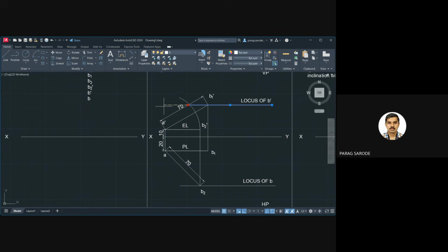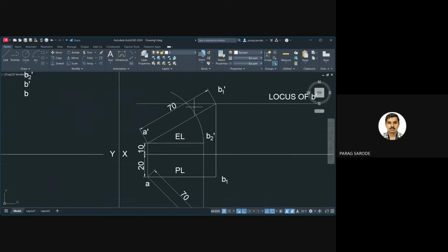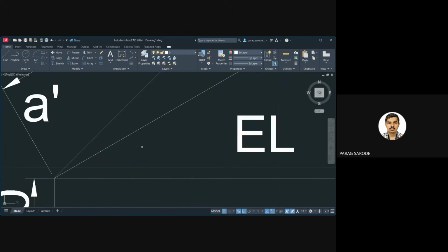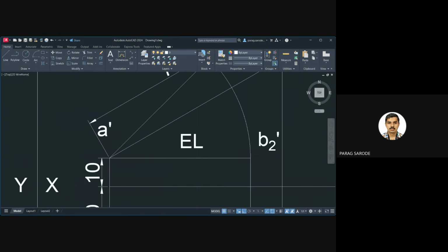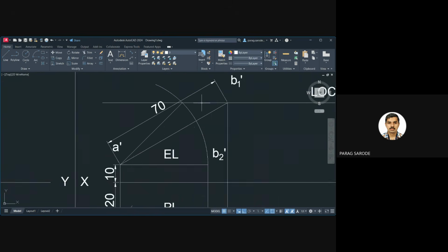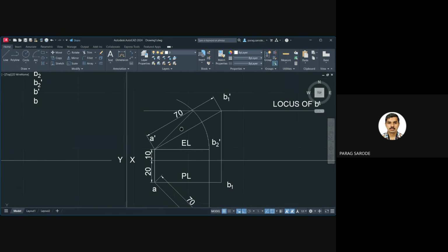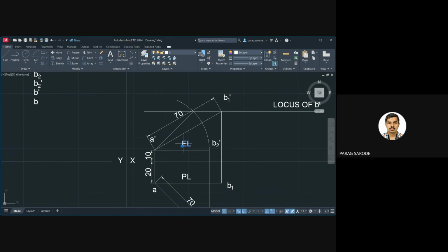Ortho mode on first before stretching. Like this. Can you see the intersection we want? Like this. While joining, carefully see whether you have joined it correctly or not, and by enlarging it. Now, what is this particular line? It's a front view length, correct? It's the front view. We'll copy this. So it's the FV, and we can write down what the length of the FV is.